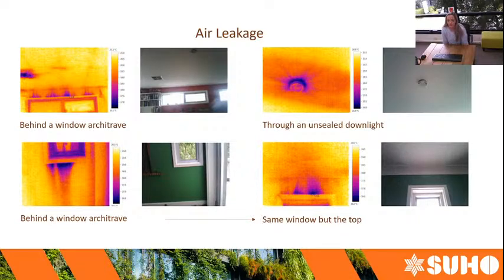The person who did the energy modelling had all the best intentions, and the design had all the best intentions. But when it comes down to how the building actually gets put together, you can see that there are a few defects in how that happened. And that means that this house is potentially not a 7.5 star house. It potentially performs much lower than that because the assumptions in the software and the heating and cooling loads in the software don't match up with what was built.